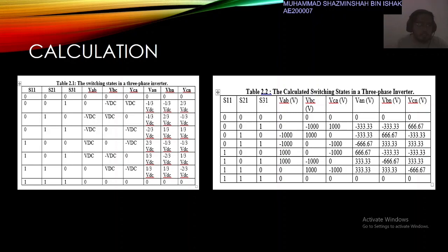In accordance to the three-phase full bridge inverter, of the 8 switch states as shown in the first table, two of them produce zero AC line voltage at the output. In this case, the AC line current freewheels through either the upper or lower component.